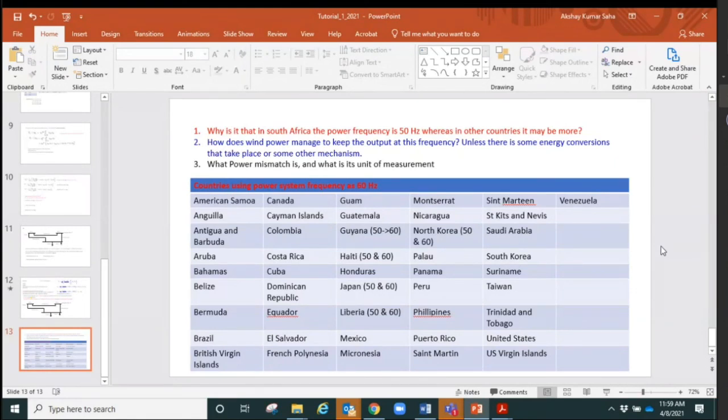You will see the effect of each other everywhere. So if you reach the limit of the generator controls, exciter control, then you have to go for shunt capacitance connected in the system that will supply some reactive power and boost the voltage of the buses.